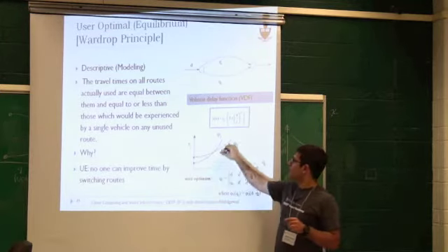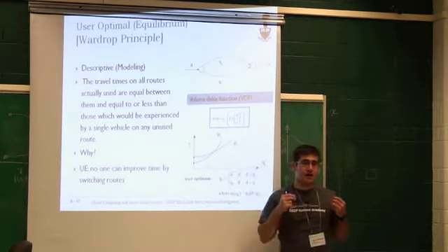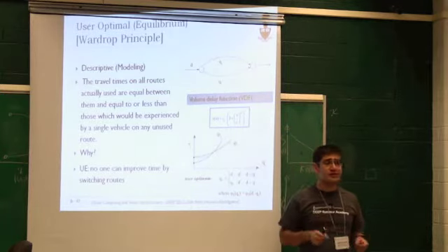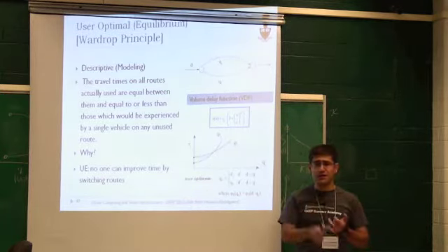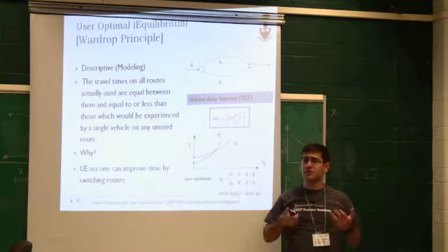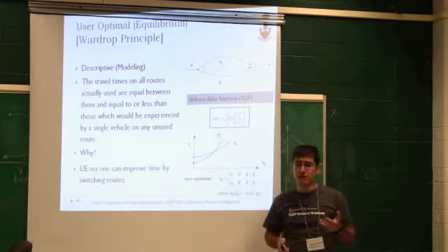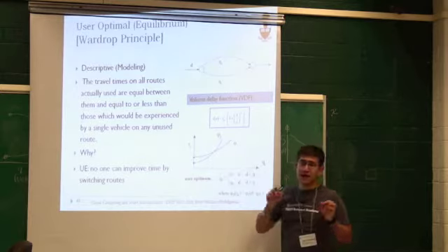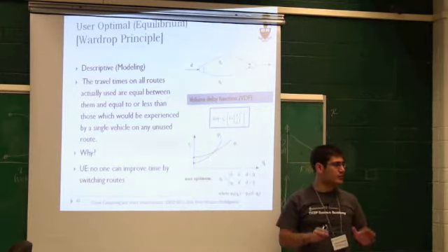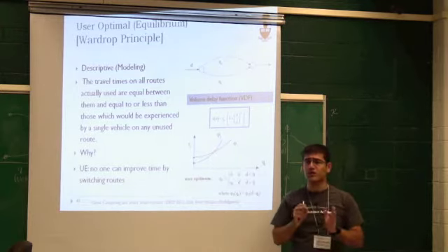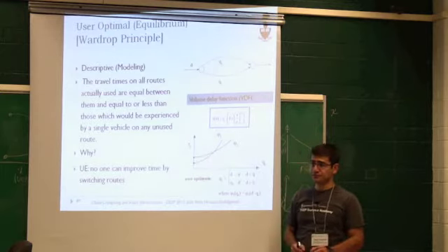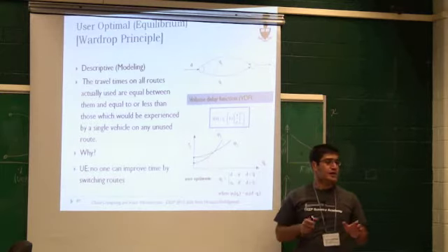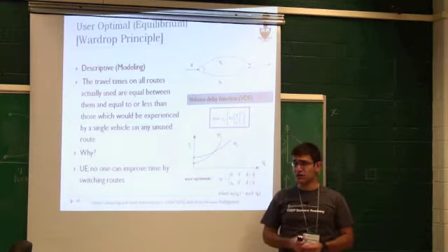Even though your original performance functions for the different links are different, they might not be the same distance, they might be slower, they might have different free flow speeds, but the ending result with user equilibrium would be that any road would take you the same exact time. Okay? So any questions regarding user equilibrium?